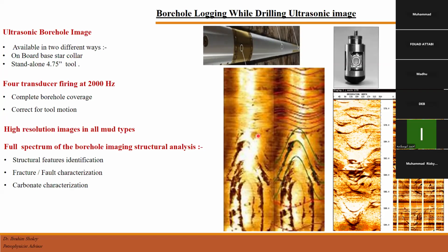First, we have piezoelectric transducers, which can emit short ultrasonic pulses, commonly ranging from 250 to 800 kilohertz, into the surrounding mud.